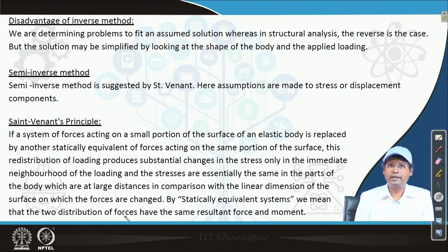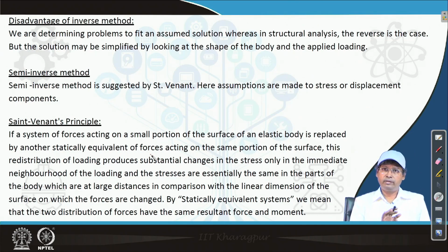So, it says that if I replace it by a statically equivalent force system, at the vicinity it is not the same case, but at some distance it is the same. And that distance is governed by the linear dimension of the surface on which the forces are changed.